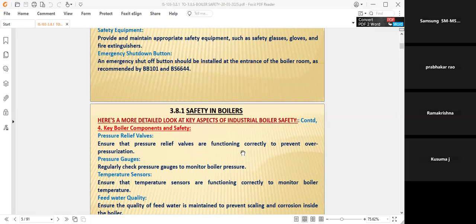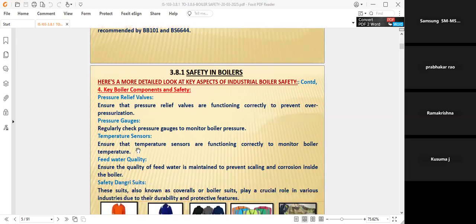That's why stagnation will occur. At that time the pressure gauge will not function properly. Immediately you have to blow down for about 3 to 4 seconds. Therefore, the line pressure will be made all right by watching the pressure relief valve. By that time, the steam drum level is also maintained properly through the charts. That means the system, the pressure relief valve, is very important.